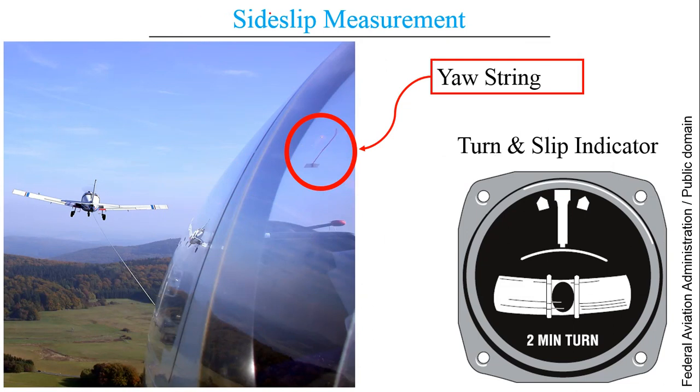Now, how do we measure this side slip in a real case? In basic gliders, we can see a yaw string. A yaw string is basically used to see the difference in yaw, but it can also be used to measure the side slip. Here we have a headwind in a straight direction. This is nothing but a string taped to the canopy of the glider. When we have a headwind, the yaw string is straight. When we have a crosswind coming from this direction, there will be some relative wind, and this relative wind will act so that the yaw string will be tilted to this direction.